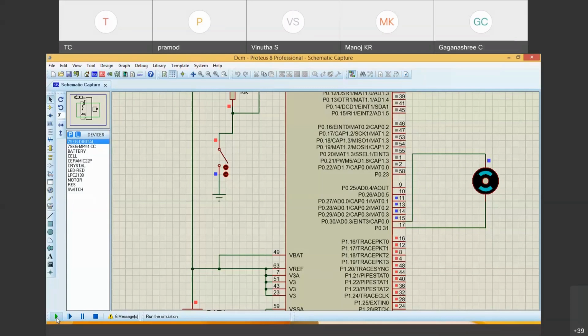Try that. So observe it's rotating. Correct? Clockwise once, anti-clockwise once. You can cross check. You can interchange and see how exactly it happens. And for example, if I increase the delay, let's assume I'll stop this, and I will change the delay in my program, which I'm not showing you. In Keil, instead of 1000, I make it 3000, let's say.